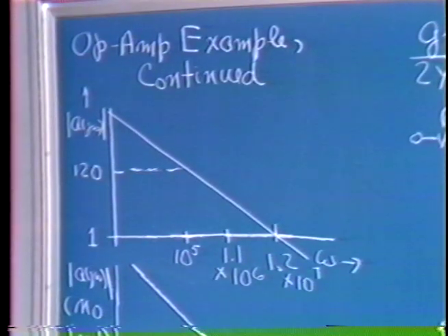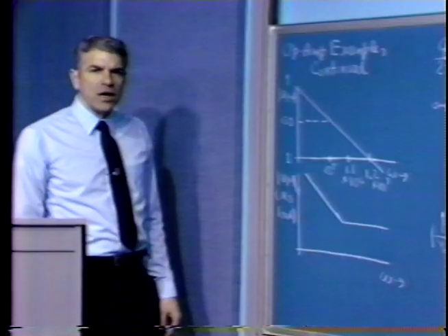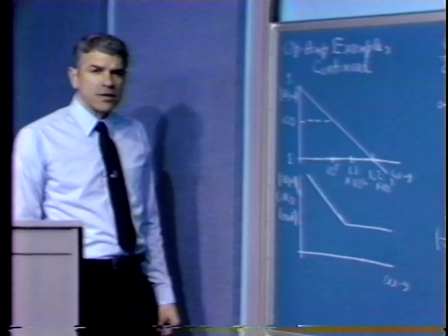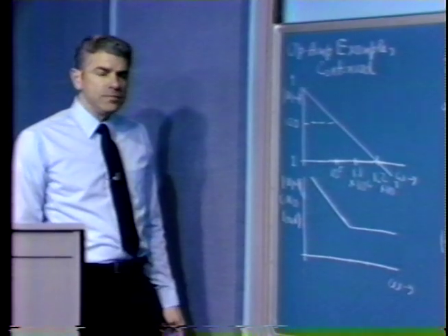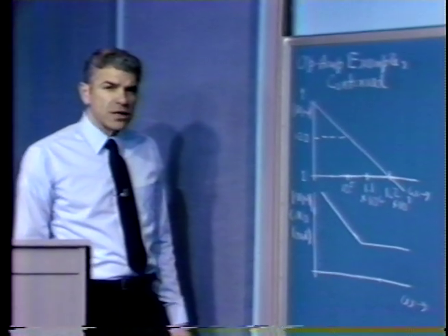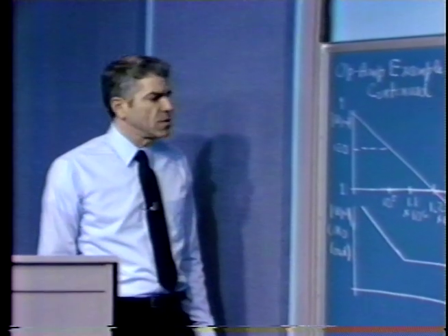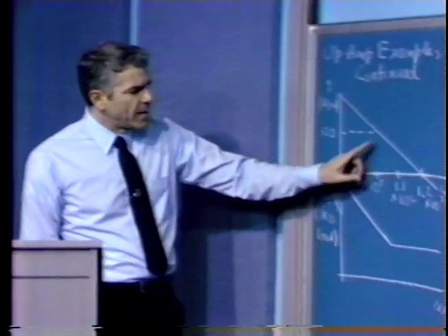The output resistance of the amplifier is somewhere on the order of 100 ohms, and consequently, when we load the amplifier with a 1/10 of a microfarad capacitor, we'll put in another pole with a time constant of 10 microseconds. In other words, we'll add a pole at 10 to the 5th radians per second, back about in here.